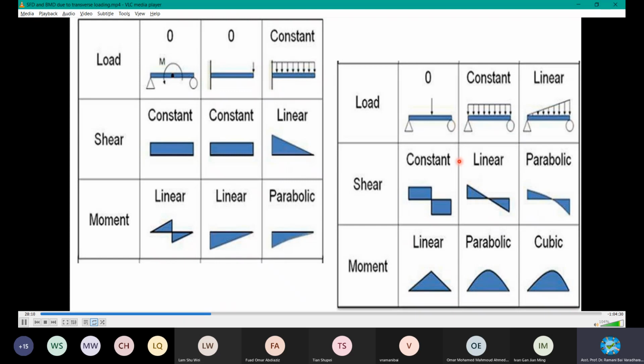And then coming to this diagram, point load. This is all about loading and moments. Again, point load at this point, similar explanation. When it is acting at this point, there is a reaction. No moments at the ends for this type of simply supported beam, because it is not restrained. It can freely move, that's why moments are zero at the ends.